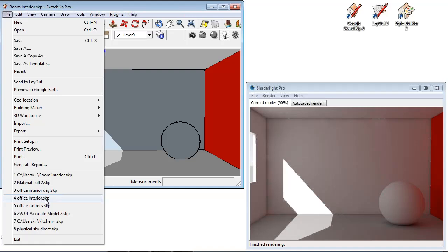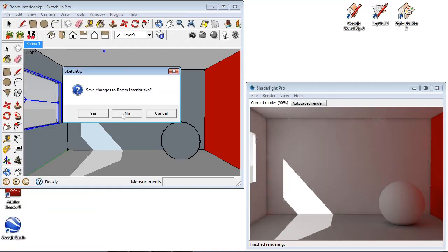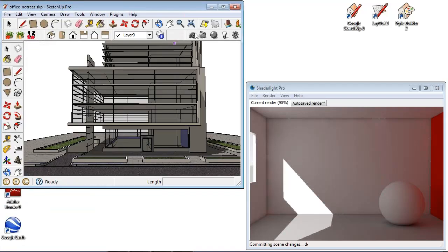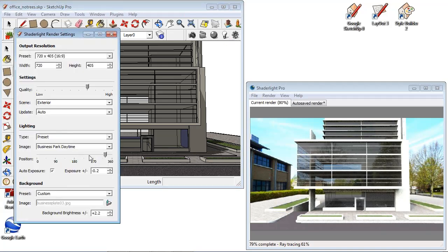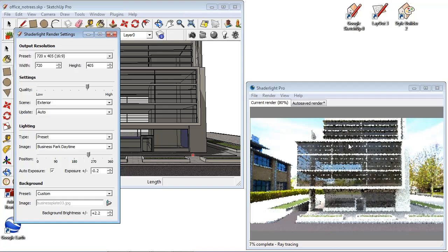Okay, so what I'm going to do now is, one thing I just want to mention regarding the lighting environments. I've got just a very simple office building here. Those lighting environments, as we said, you pick up the colours and things like that, but they pick up reflections. We're in that 360-degree photo, and we can see in the windows of this office the trees reflecting from that 360-degree photo. So if I rotate my HDR, we'll see the position move, and we can get a different set of reflections in there.